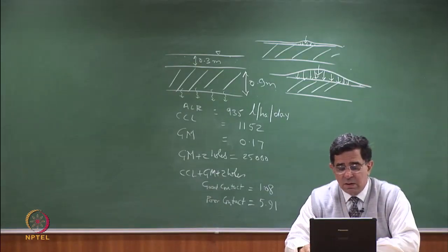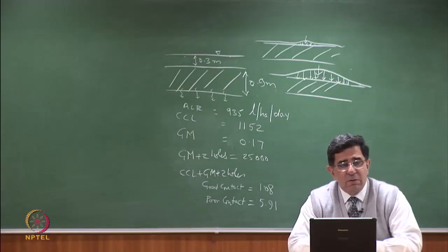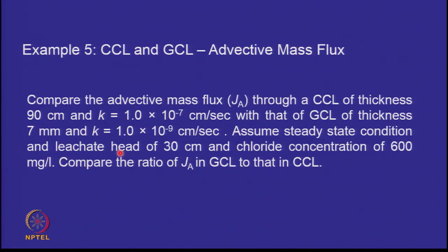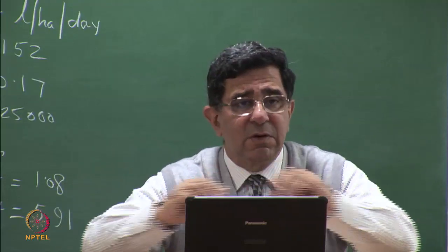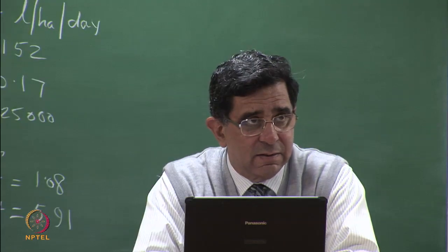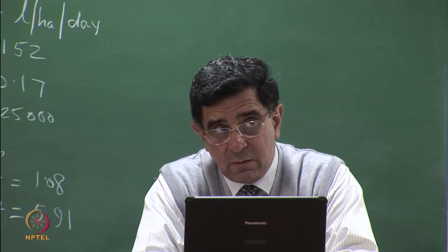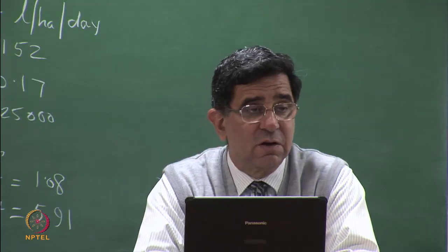Questions, then we would like to go to the issue about comparing compacted clay liners with geosynthetic clay liners. Okay? You recall that we had said that if you can get low permeability thin material, then it can also perform as well as a compacted clay liner. So I am going to compare 4 aspects of this comparison.